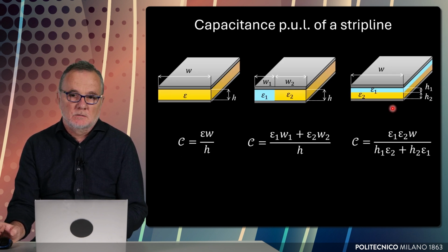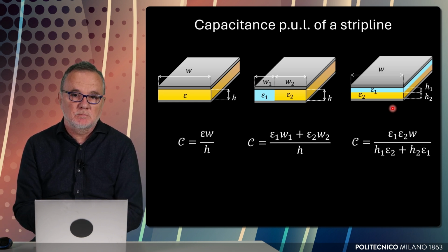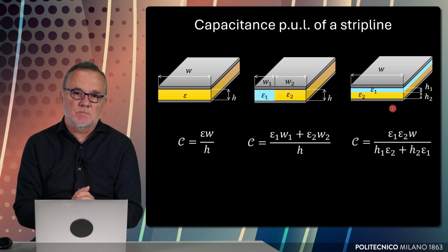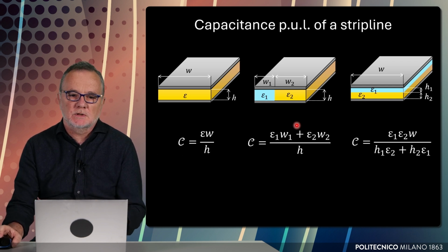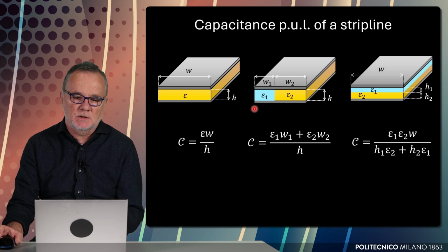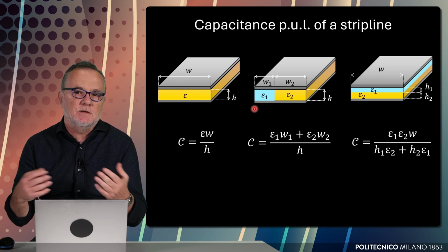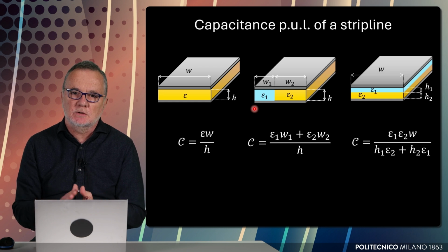In addition to the capacitance of two electrodes in 3D, two metallic bodies in 3D, we can also define a capacitance per unit length for an infinite length of conductors in space. Of course, if the two conductors have an infinite extent in length, the total capacitance is infinite, because when you apply a voltage difference, there is an infinite amount of charge. But a unit of length corresponds to a finite amount of charge, and therefore this finite amount of charge can be divided by the voltage difference to define a capacitance per unit length.